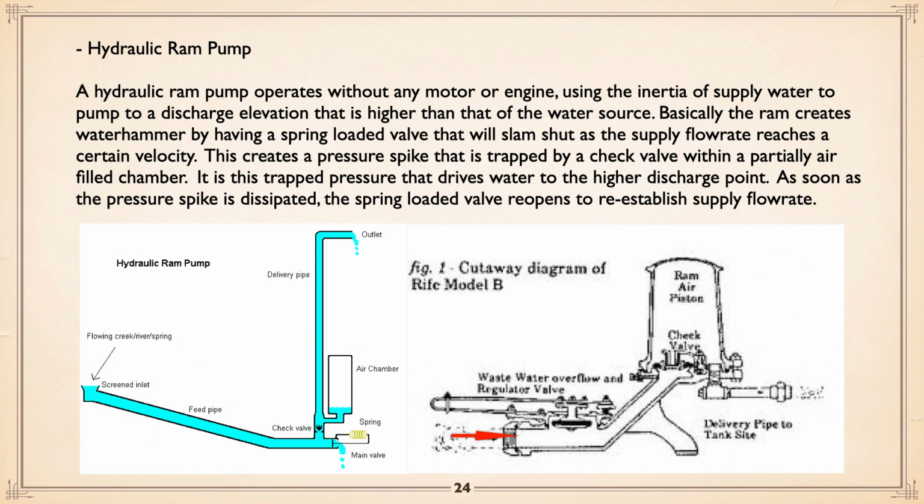Another very interesting concept is a hydraulic ram pump. Basically what you've got here, let's pretend you have a stream down below and you have a house built at the top of a cliff. The water's down there, you're up there. You'd like to get water, but there's no electricity, so what do we do? Well, what you do is you pull a pipe off the stream and bring it, as you can see down, looking at the left drawing, as that blue line comes down, it flows out, and you notice there's a kind of a weird little valve with a spring on it.